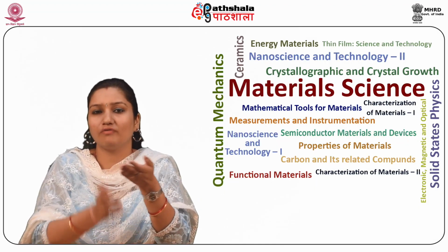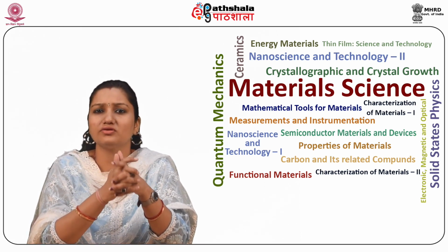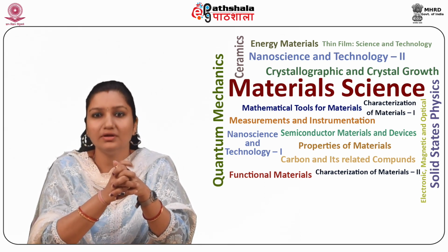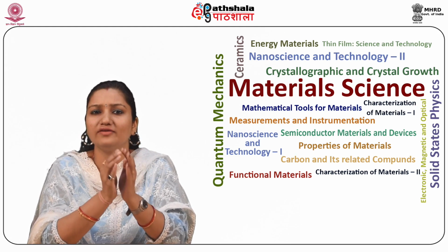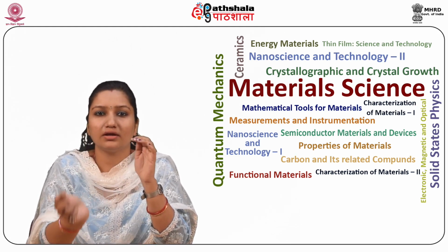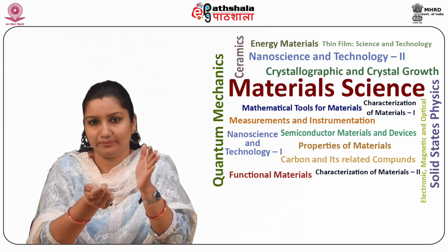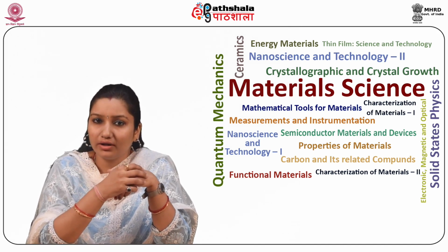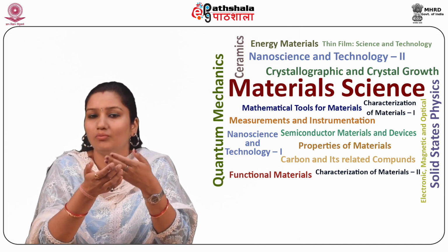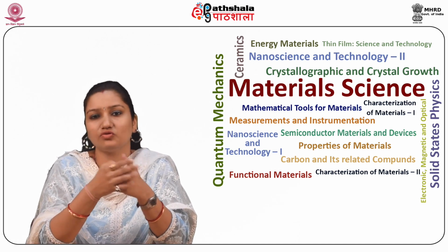Other advantages of using magnets are: number 1, lower voltage needed to strike and sustain plasma. That is, magnets produce a localized magnetic field due to which electrons move in a curved or helical path near the target. Curved paths are longer, which promotes more collisions en route. More collisions make more ions, and thus it gets easier to strike the plasma.